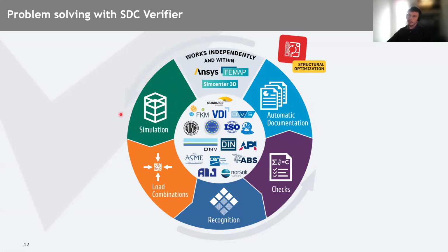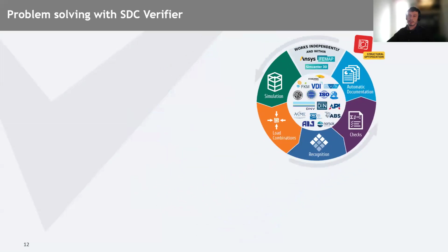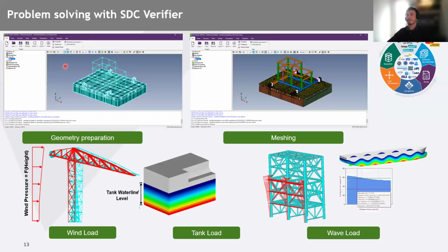So the first part of the workflow is the simulation. As I said before, simulation consists of modeling our geometry and meshing the model to capture all the spots. The mesh should also be refined in the areas where we expect some overshoots, or where we would like to have more accurate results.